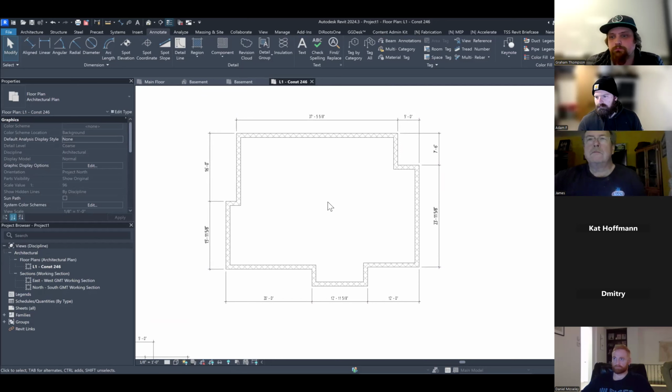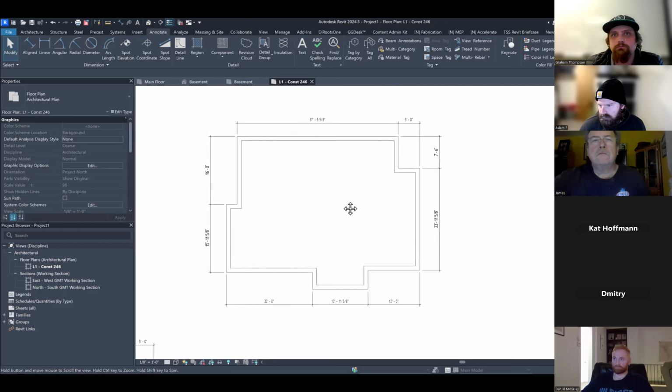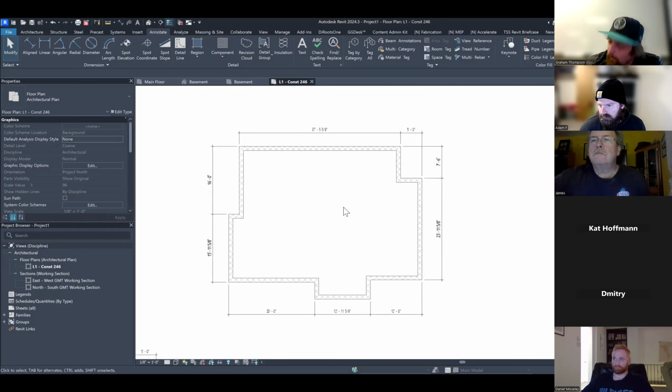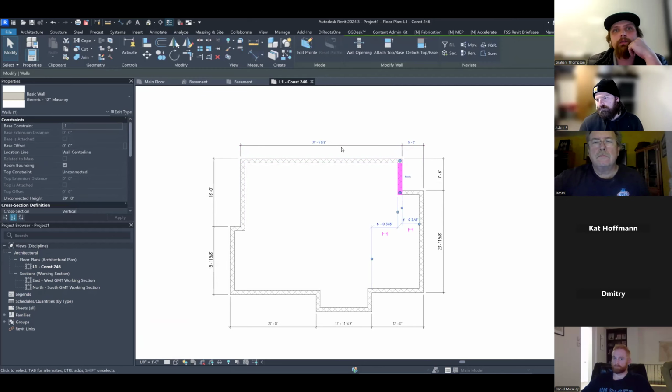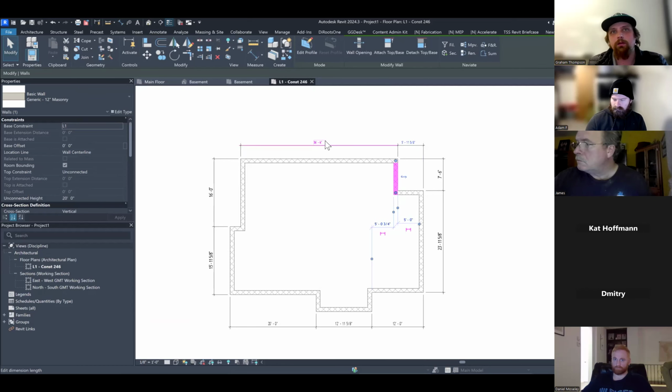Select the wall and type the right measurement. Absolutely. Very good, right? Simple as that, right? Now that we have the dimensions that we need in the places and or locations that we want them to be dimensioned to, we can simply just click on this wall. That dimension activates, and I can type in 36 space 6, and now that is outside to outside of those walls, right?